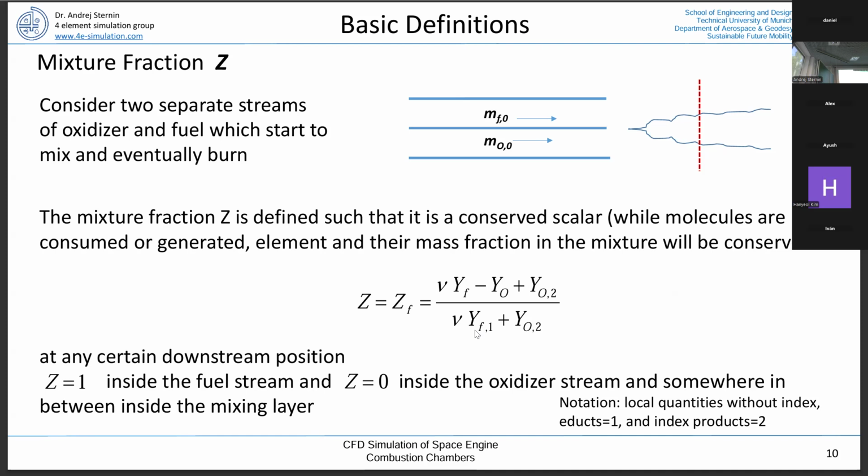Then we can say, in a non-premixed condition, or even in the premixed condition, we have cold flow coming from one side, and at the stoichiometric mixture fraction, this is the flame, and on the other side of the flame it's product. So a large number of combustion models work that way: finding the stoichiometric mixture fraction immediately gives you the position where the flame is.